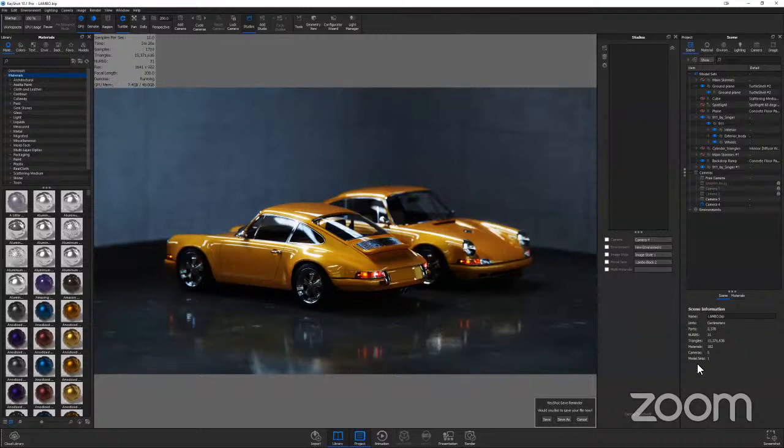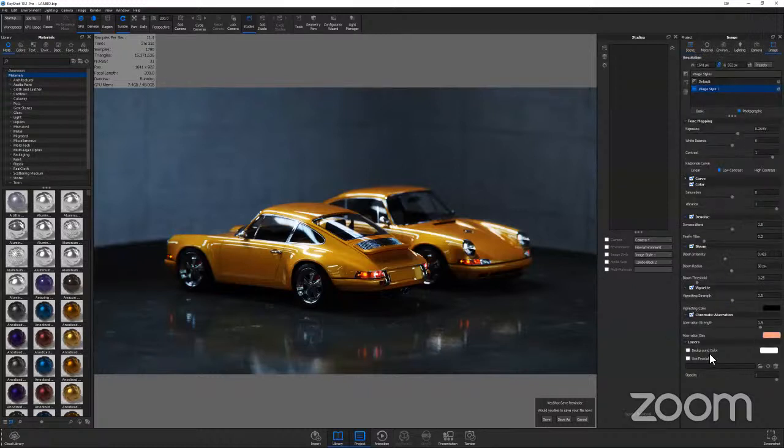Yeah, great question. Thankfully, KeyShot already has the answer. We use a lot of front plates and back plates. So we'll use this front plate tool here, which you'll see in the image bar. What we can do here is have our PNG and put it in as a front plate if there's going to be depth in it, if there's going to be something in the foreground or something in the background and our product's going to sit somewhere in between the two. We'll be able to apply that front plate, measure it up, make sure the size is all there, and then even have our background image in there as well. That way we can composite and superimpose those three images together.